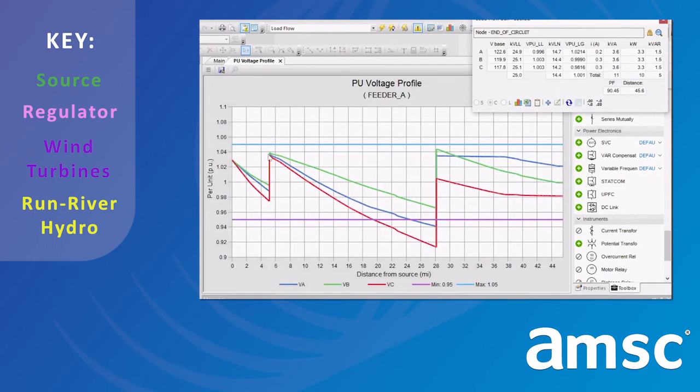So in the first regulation zone, the voltage drop is from approximately 1.04 per unit to 0.9 per unit, or more than 10%. Since a typical regulator can boost up to 10%, you could not resolve this voltage issue with a different type of control setting at the regulator. You'll either create high voltage on the front end of this regulation zone or have this remaining low voltage at the tail end of the regulation zone.